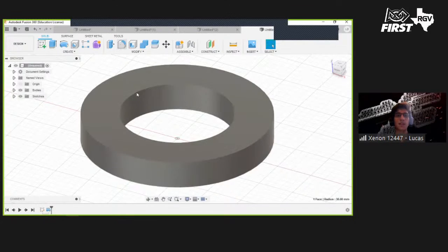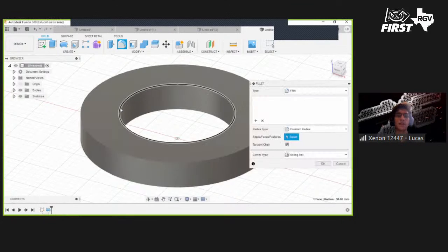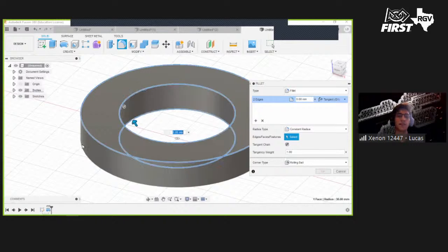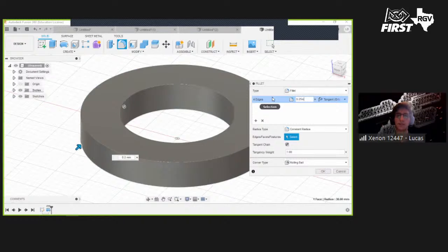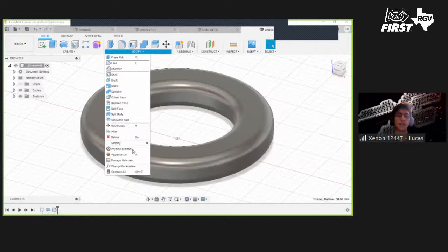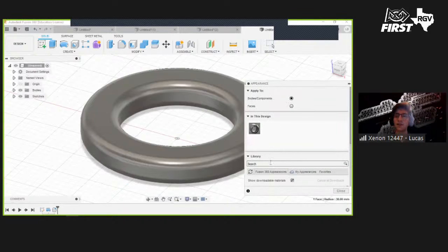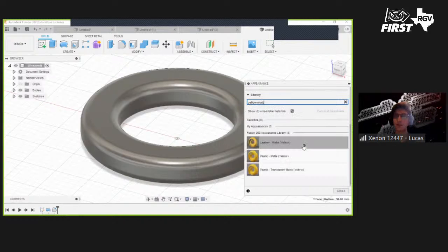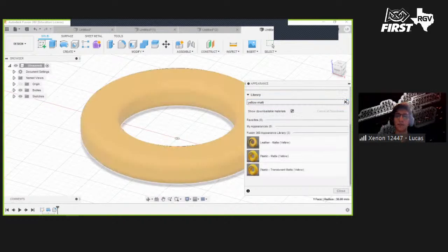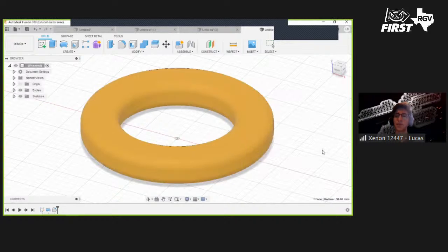Let's go ahead and make a fillet of that. Fillet, fillet, fillet, and fillet. And I'll go ahead and say 0.25 inches. There we go. And like I said, I kind of want it to look right. So I'm going to go ahead and use a yellow. Type in the word matte afterwards. And say plastic yellow. And there we go. So notice, that's 2 different ways of creating the same model. And so here are our 2 different sections.